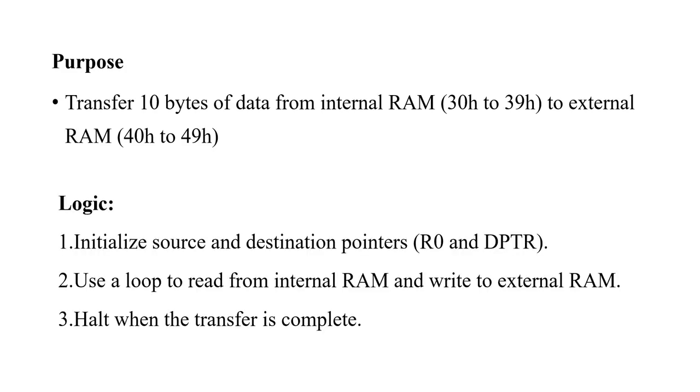So the logic of the program is: the first step is to initialize the source and the destination pointers, that is R0 and DPTR. The second step is to use a loop to read the data from the internal RAM and write it to the external RAM. Then we'll halt the program when the transfer is complete.